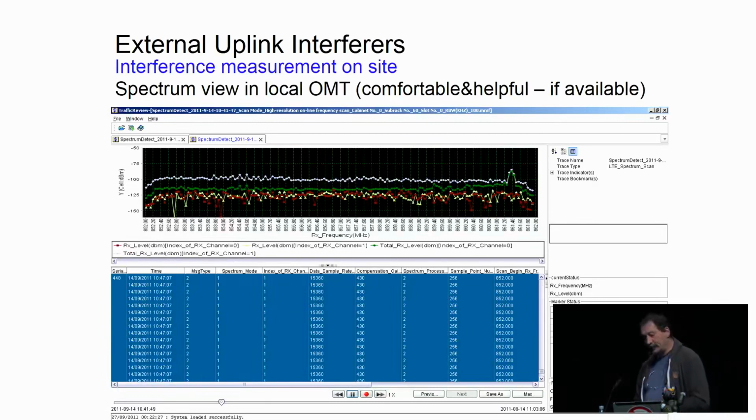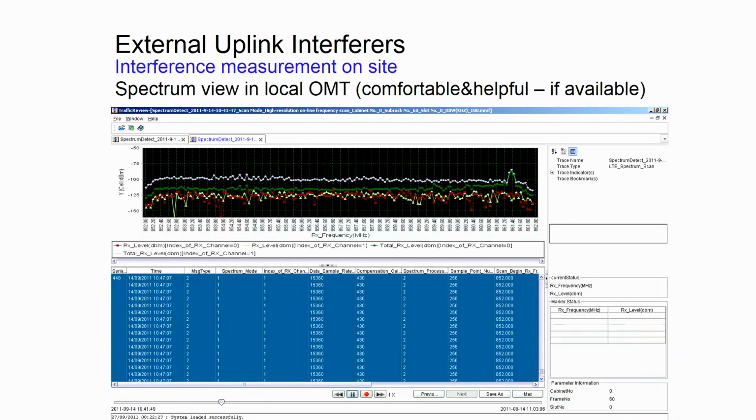You can measure at the site, and if you have received a trigger as a field service technician, I go there, and some manufacturers have this spectrogram, and directly at the station I can look at the uplink spectrum, and you can see the white curve. The white is bigger than the green, so some of the antennas is perhaps broken there, and you can look at it in more detail, change the power, turn off the power and turn it back on, and you can see that this is a modulation problem.